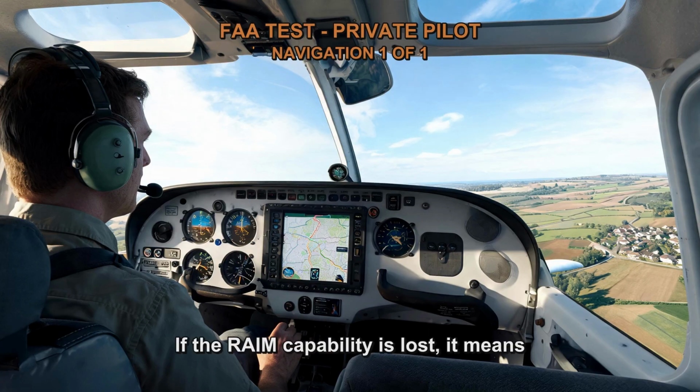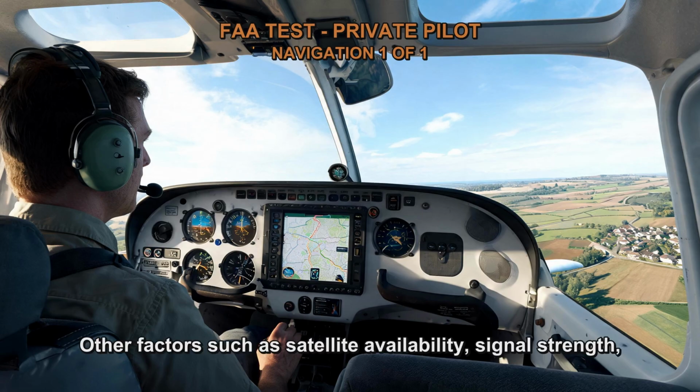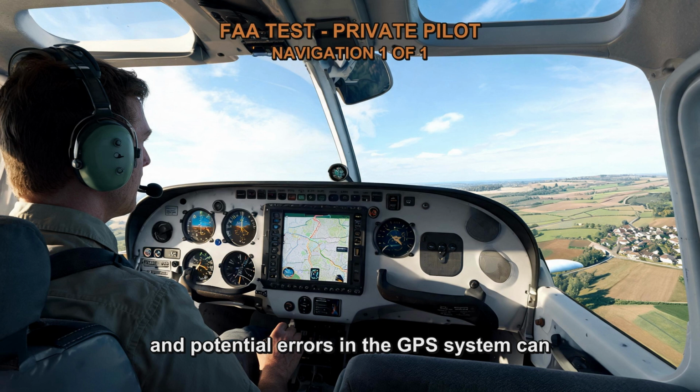If the RAIM capability is lost, it means that the GPS receiver is unable to verify the integrity of the GPS signals it receives. Without RAIM, the pilot cannot be certain of the accuracy of the GPS position. Other factors such as satellite availability, signal strength, and potential errors in the GPS system can affect the reliability of the GPS position.